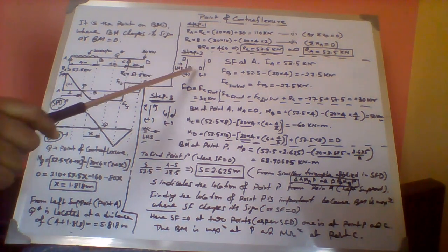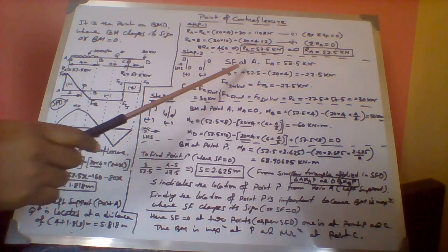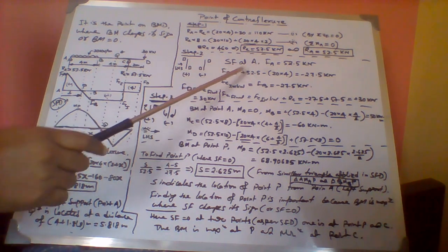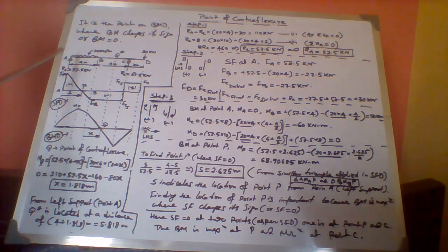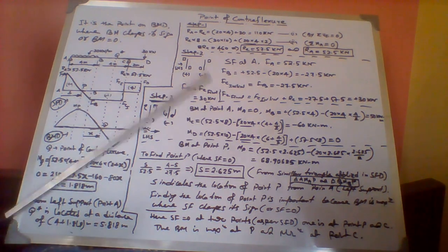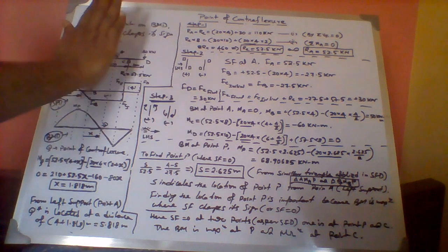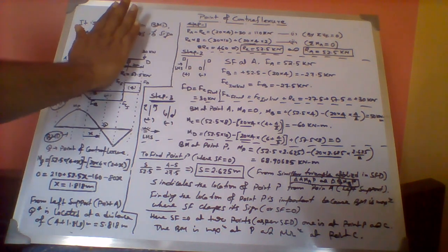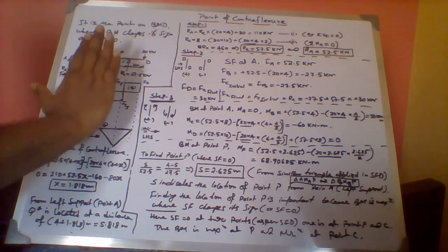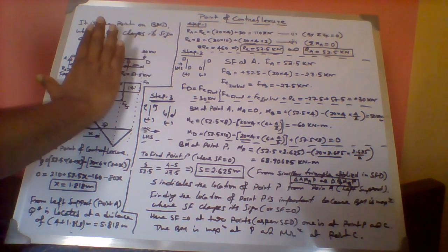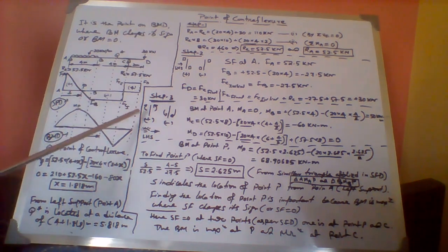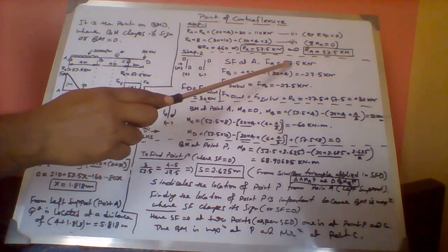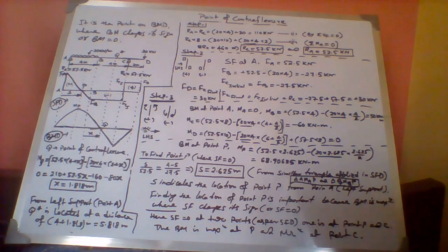First, draw the corresponding sign conventions, as you know. So now we are trying to find the shear force at each of the points. So FA, here we are going to look from the left side of the beam. If you want to calculate the F at A, you should put your hand like this. Now see, you can see from the left hand side. Can you see from the left hand side? Yeah. So there is a force FA moving in the upward direction. So upward from left is positive, so it will be plus 52.5 as the value of RA.